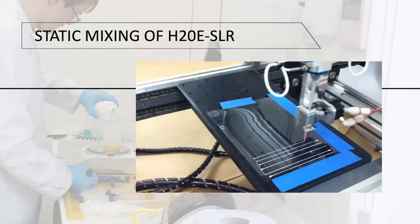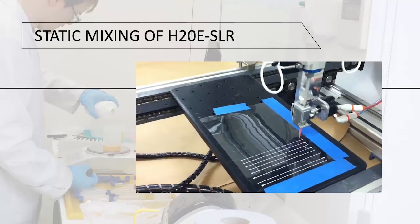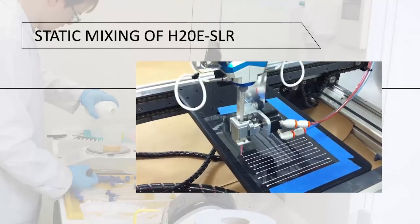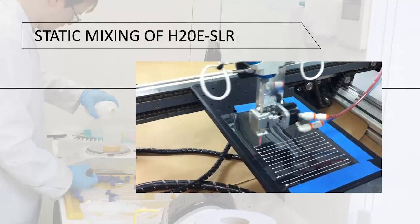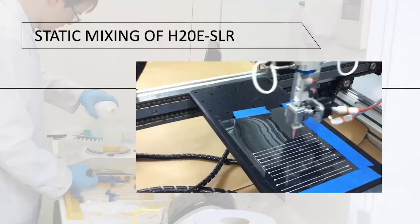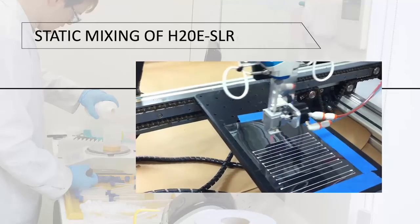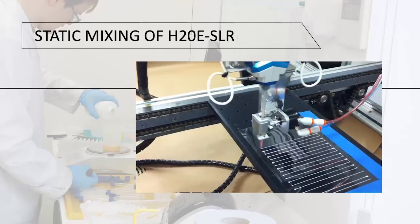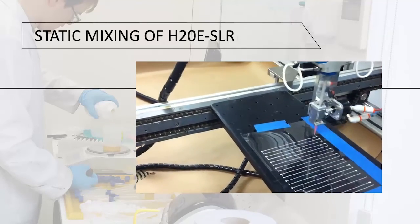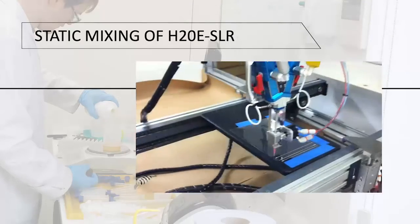In the video, you can see a static mixing system mixing the EPO-TEK H20E SLR that is utilizing one of the helical mixing tubes to mix the A and B together, and you can see it dispensing bubble-free, void-free, straight lines, great in this case for solar ribbon attachments.